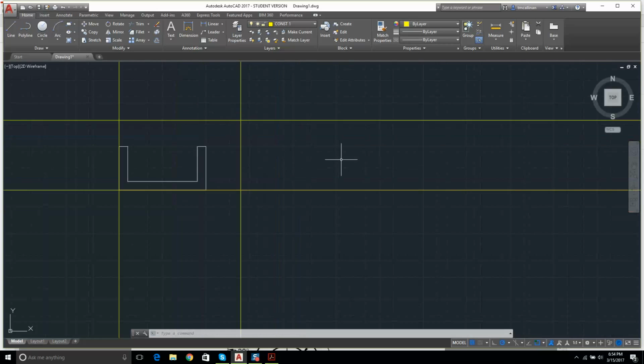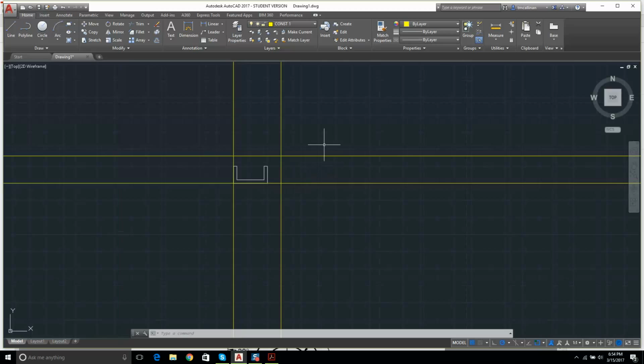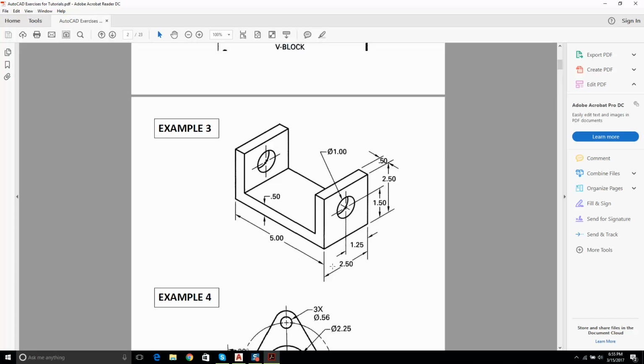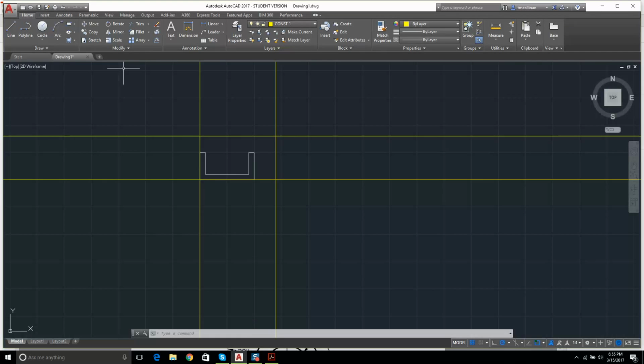That'll do. Now, what I'll do here is I'm going to draw the side view. Now, what does the side view look like? It comes over 2.5 and up 2.5. So this front view is looking in from this direction. The right hand side view is looking in from this direction. And it's a rectangle. And that's going to be my first point.